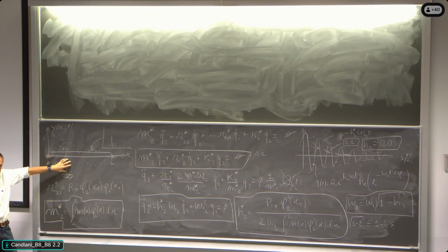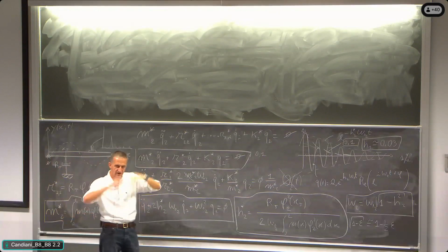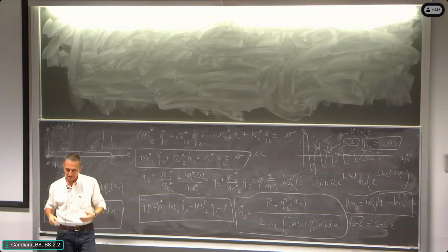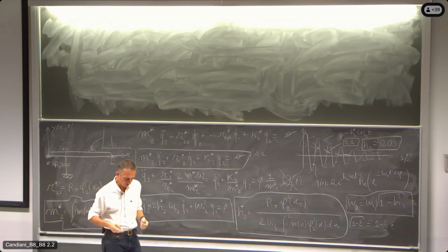So if I am adding a lot of damping, and the non-dimensional damping of mode 2 becomes 20% or something like that, then all the modes are mixing together and I am not recognizing the separated modes anymore, all right? So it depends a bit on the numbers.